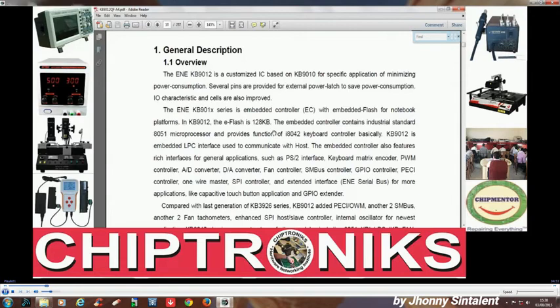With the initial file, right? You get my point? This embedded controller requires programming after soldering a new IO controller because it has an embedded flash. So we have to change the program of that flash also. You can see this is a very interesting problem, a very interesting case in fact.